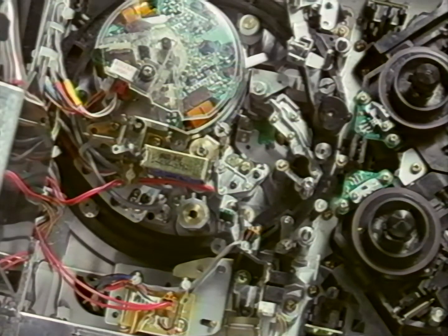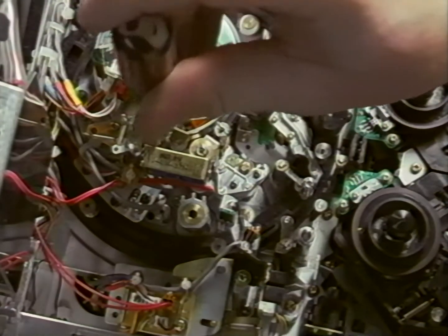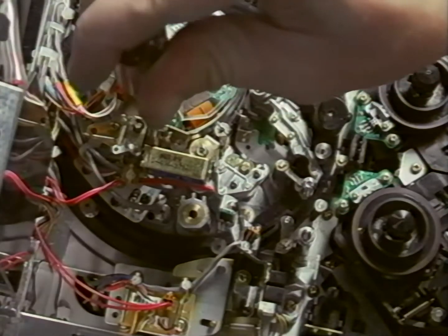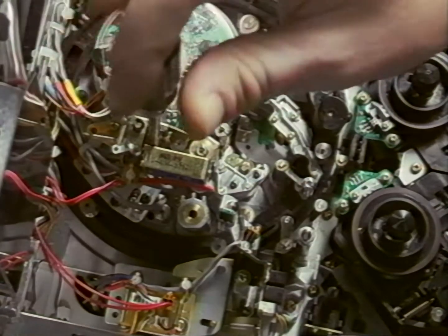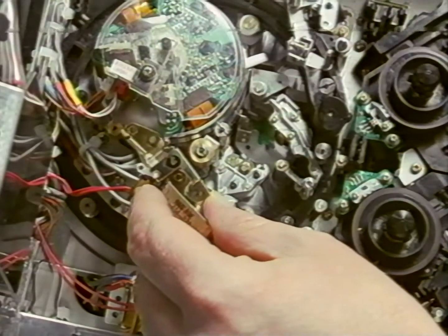Audio Timecode Head Assembly. The procedure described in Section 5 of the Service Manual is the replacement of the audio timecode head, which takes much more time to remove and replace than replacing the complete assembly. This is because it takes desoldering and soldering 6 wires and many adjustments to align an individual head.